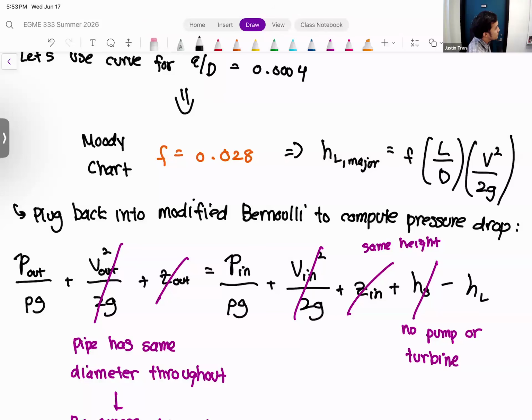So could we use this, because from the engine to the connecting pipes, it would be like four 1-inch pipes connecting to one 2-inch pipe and then it goes out the rest. Can we use that formula? Although I would say that generally for air, I don't think viscous friction is that big a factor in that situation, because you're outputting to atmospheric air at the end. I don't think the losses are going to be that high if it's air.